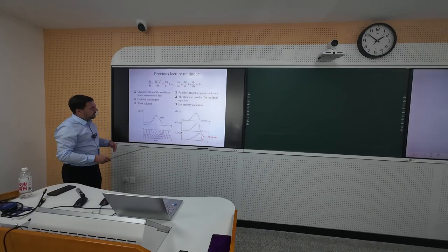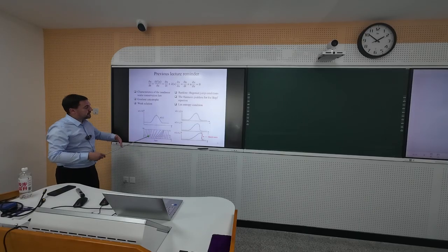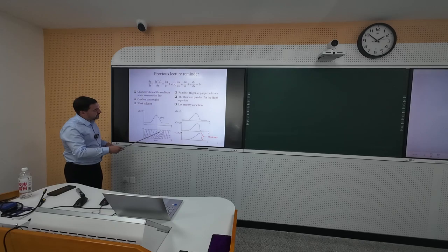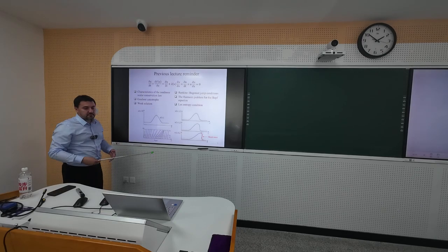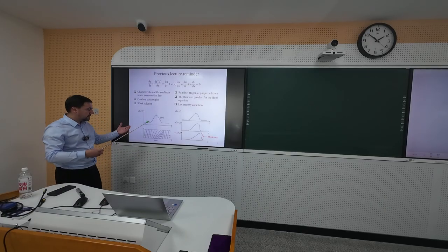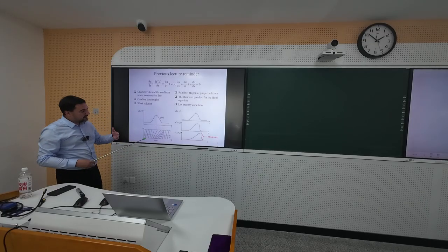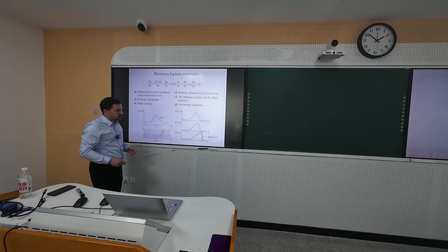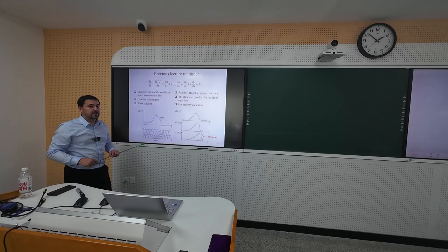In this case, for sure, we have a situation when characteristic lines intersect. But the characteristic line is the line along which our solution propagates. It means that at the point where the characteristic lines intersect, we do not know the solution, because on one hand one characteristic corresponds to one solution, another to another. The only way to resolve this issue is the formation of a shock wave or discontinuous solution, in simulation or from a theoretical point of view, it doesn't matter.